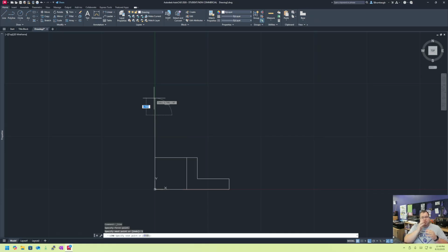And from there, I'm just going to draw the rest of the top view exactly the same way we did the front view. So we're going to come over 1.5. We're going to go down 1, over 2, up 1.5, back this direction towards the left, 3.5, and then down. And I'm just going to click this one. And with that, we have the outline of the top view done, and then we have these lines that we can just select and delete. And it's as simple as that.